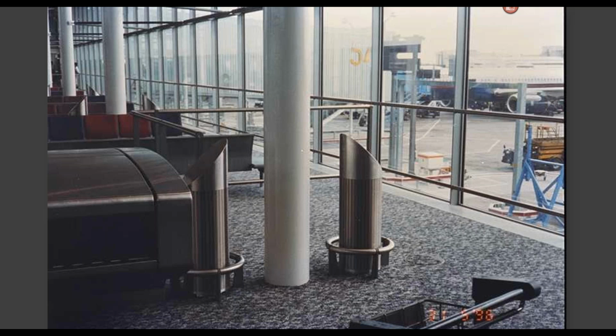These particular units are made out of stainless steel, so they are very robust. But this works great for this space because it is an open floor space. You have glass walls, which would make it very difficult to introduce air through that surface, and you have a high ceiling. So this type of application is a good candidate for displacement just because of all those reasons I just mentioned.